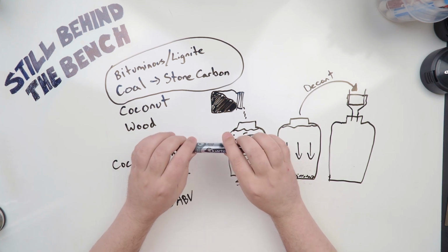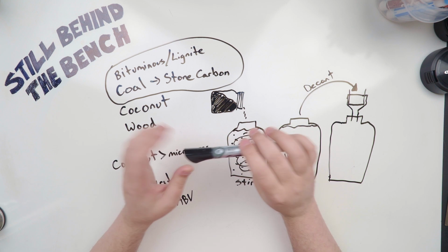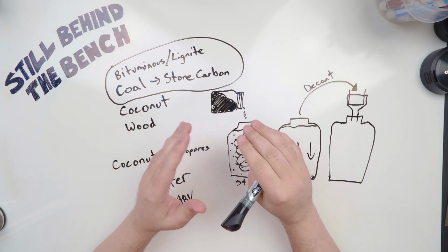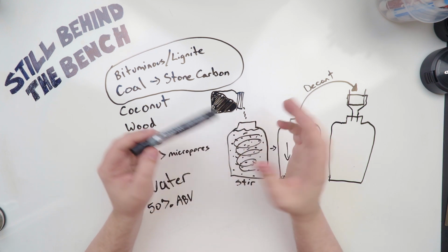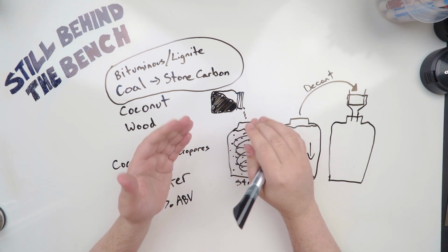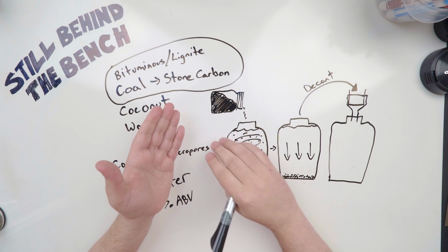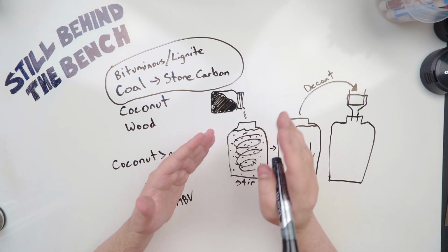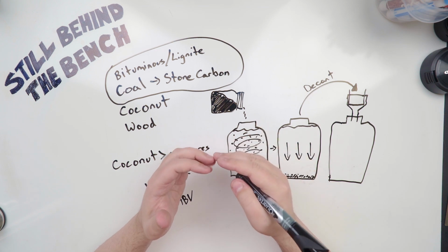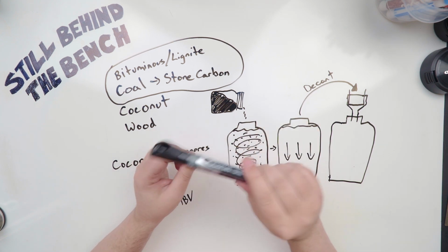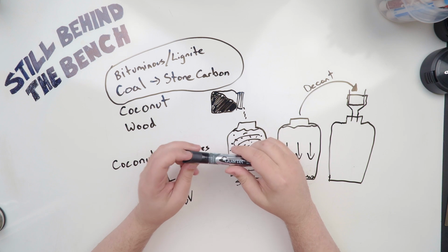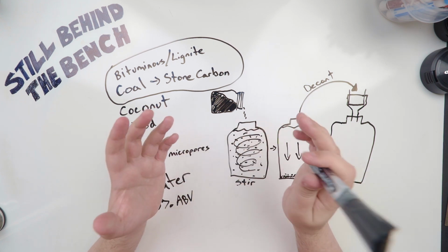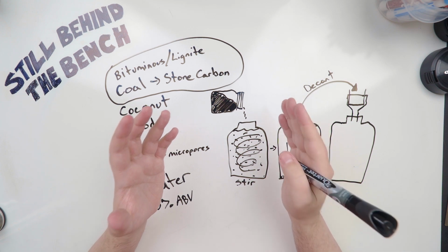But pumping and process time are linked, and the main issue is that air pockets forming can drop pump pressure and cause head loss, which is a significant issue. Pump pressure drops, head loss is formed. You may not be able to pump all the way through the filter, or it might just take a long time, especially if you can't force those air pockets out. But pumping in from the bottom, you might be able to force the air pockets out. And you may be able to prevent the wall effect, and you may be able to prevent channeling from happening.